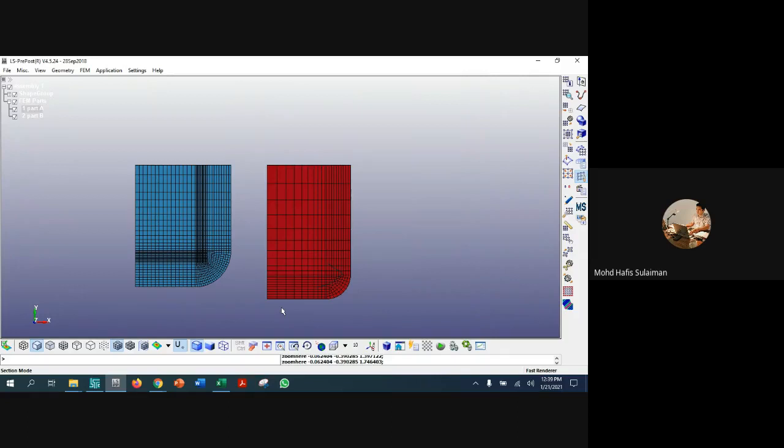That's one of the design parameters. You need to include design and process parameters. When you play around with the friction value, it means you adjust the lubrication conditions. And also with the parameters for the materials, you need to be careful about the plastic regions. So you need to know what metal model you use for your work. Anything else? I think that's it for now.